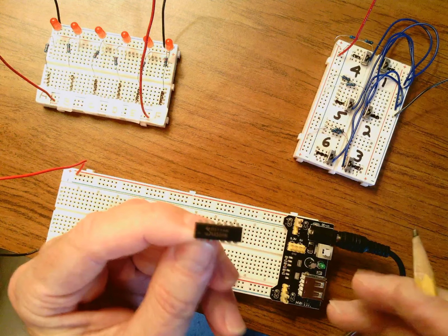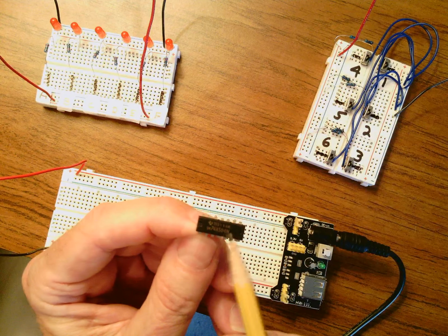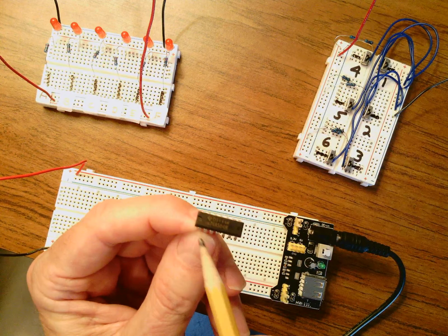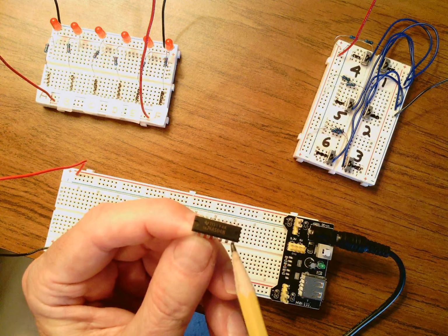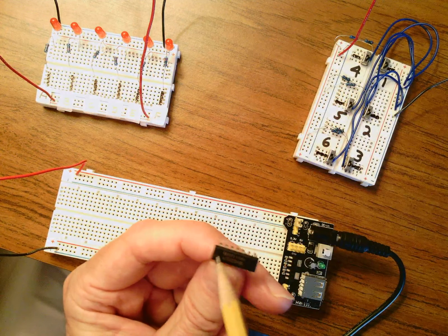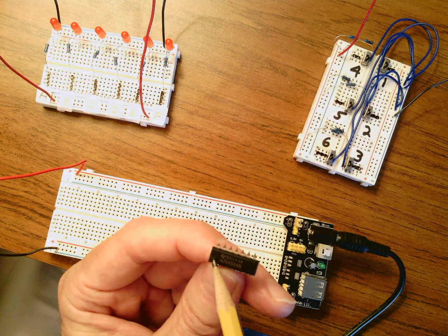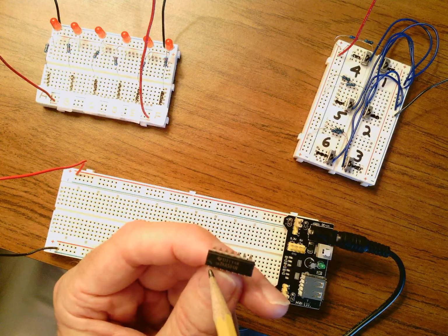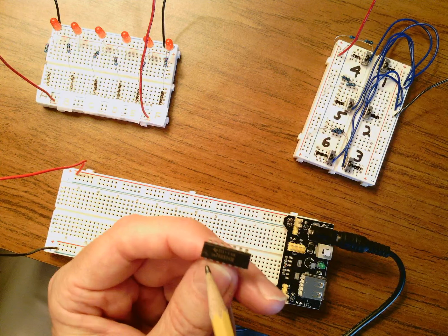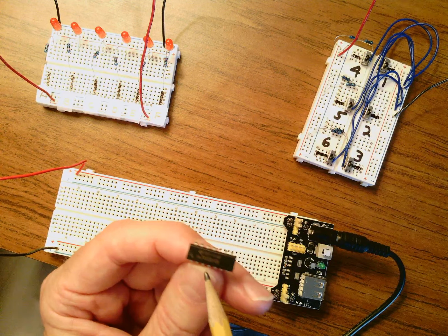16-pin packages. The 7404, which is the hex inverter, has 7 pins on this side, and on the back side it has 7. And there's a notch here. I don't know if you can see it, but there's a little notch right here. That notch allows you to identify pin 1 down here to the bottom left. So this goes pin 1, 2, 3, 4, 5, 6, 7, and then it goes to pin 8 over here, 9, 10, 11, 12, 13, and it goes to pin 14.